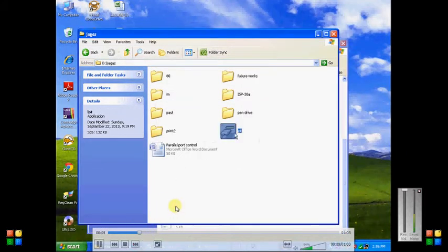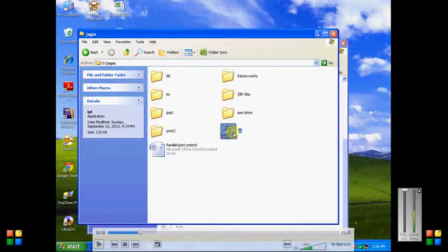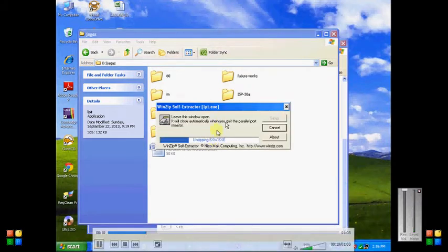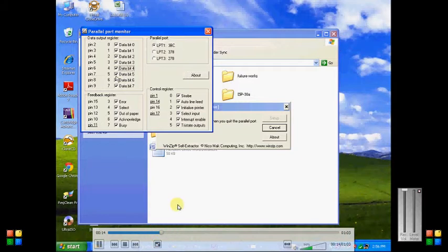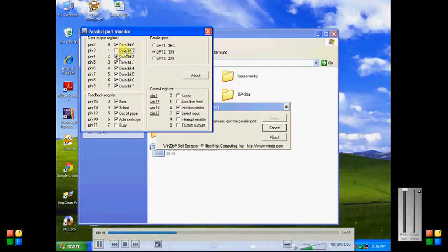Now you have to download a software called lpt.exe, for line port printer, and run it. Here you have a number of pins. By clicking on them, the status of the parallel port actually changes. Here you have LPT 378. If you select the other addresses, the parallel port is not going to work correctly. See, now I'm clicking various pins. Okay, now it is working. The parallel port status is actually changing.